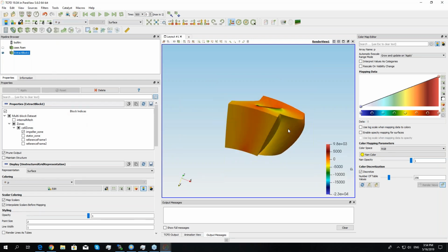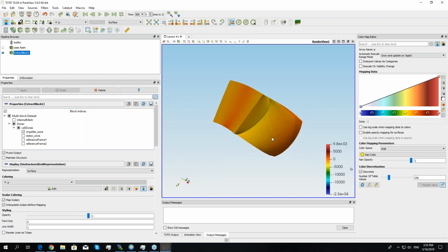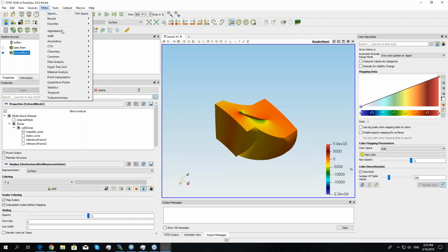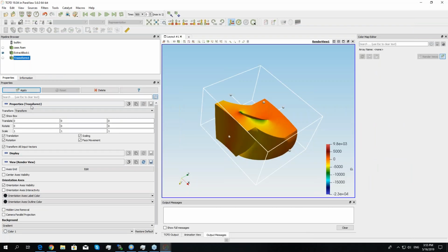And for example, now I would like to make some slice and to see the 3D blade-to-blade view. So first of all, I would like to copy the segment to see at least 3 segments, for example. So there are 2 options. The first option, which is not so clever, is to use the transform filter, which can transform anything you say.